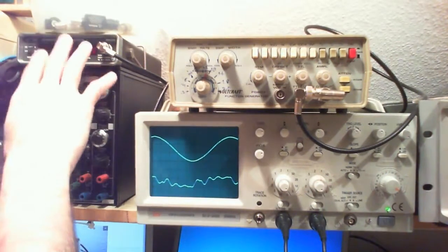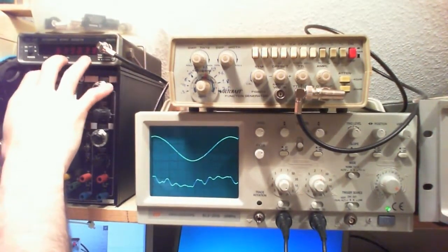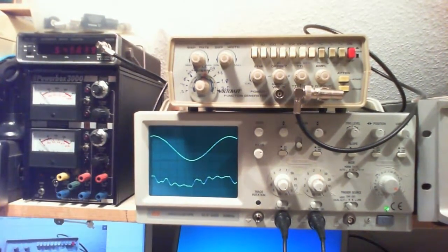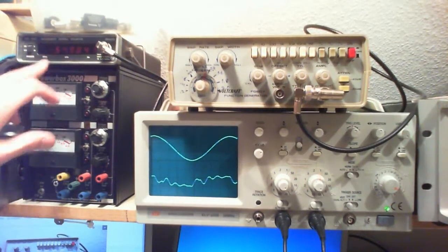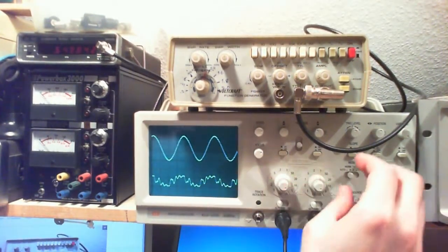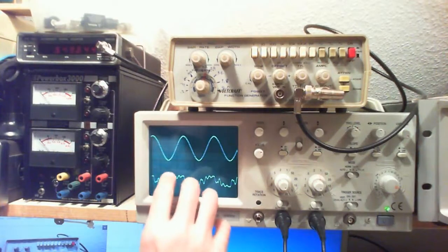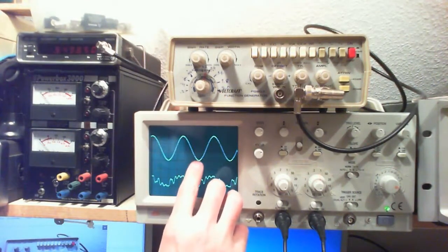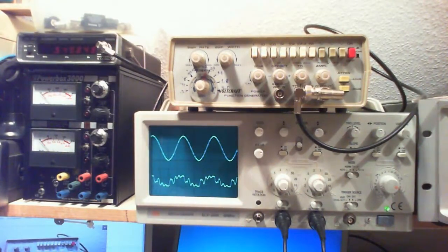because that's the point where your output is at the minimum, but I don't want to read my frequency at this point from this counter, because it's off by probably a few tens of kilohertz or so. So I come back over here and take a look at 1, 2, 3, 3.57 horizontal units times 0.5 microseconds.